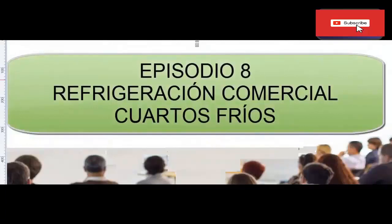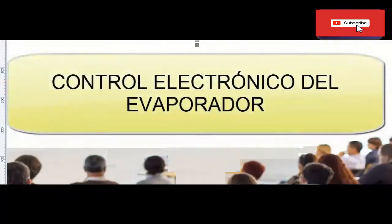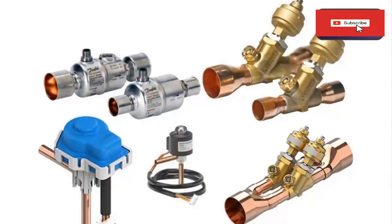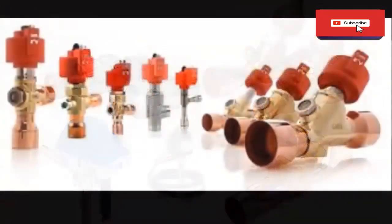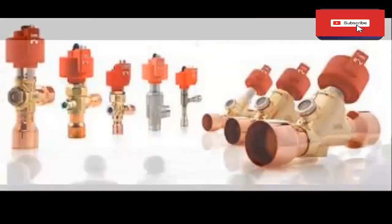Today we introduce the electronic expansion valve and the electronic evaporator controller. Well, let's start with the basic terms. What is an electronic expansion valve? An electronic expansion valve has the function of feeding the evaporator with liquid refrigerant and maintaining a fixed superheat.